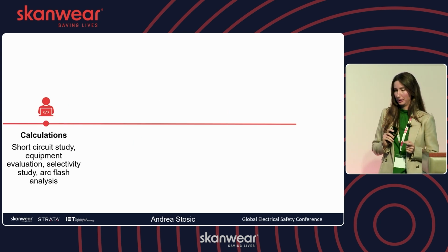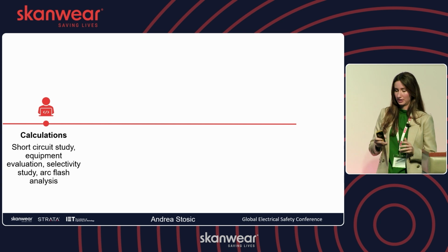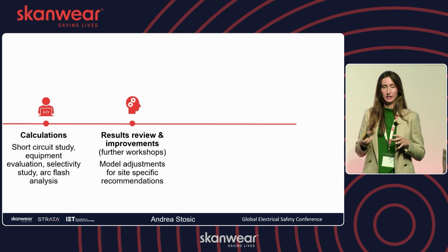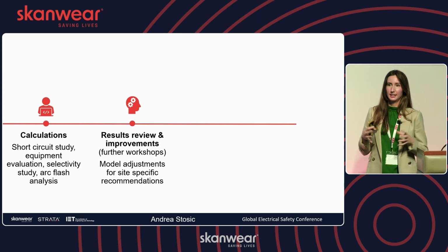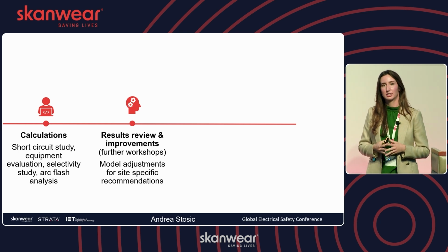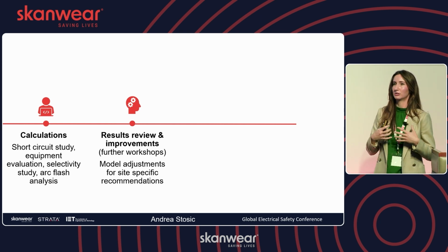The next step would be calculations. So which calculations are required? Well, we will need short circuit calculations, equipment evaluation, potentially a power flow study, a selectivity study, and an arc flash study. Once this has been done, I suggest making this a collaborative step, involving the client and the consultants, getting them to come to the table and discuss the results, the findings, the safety concerns, and the recommendations.